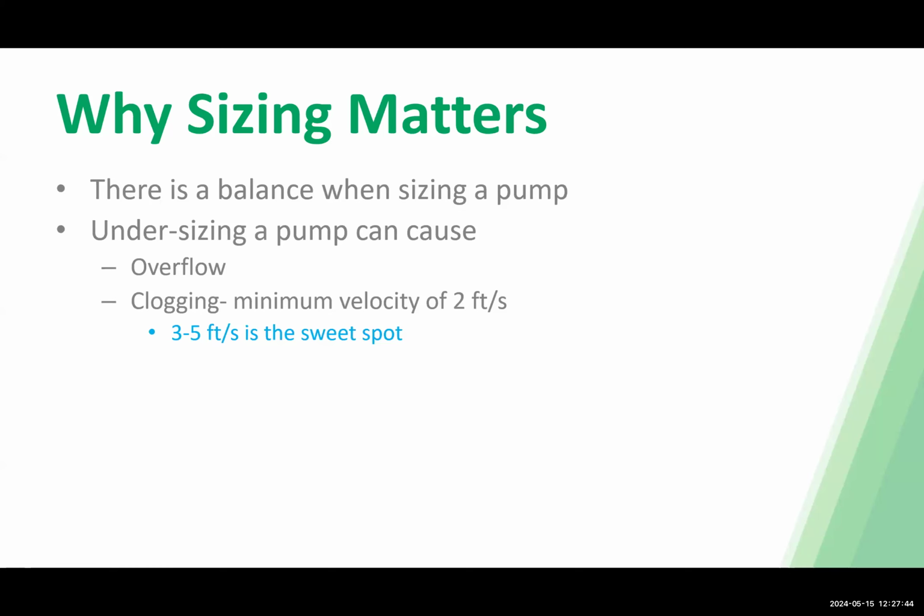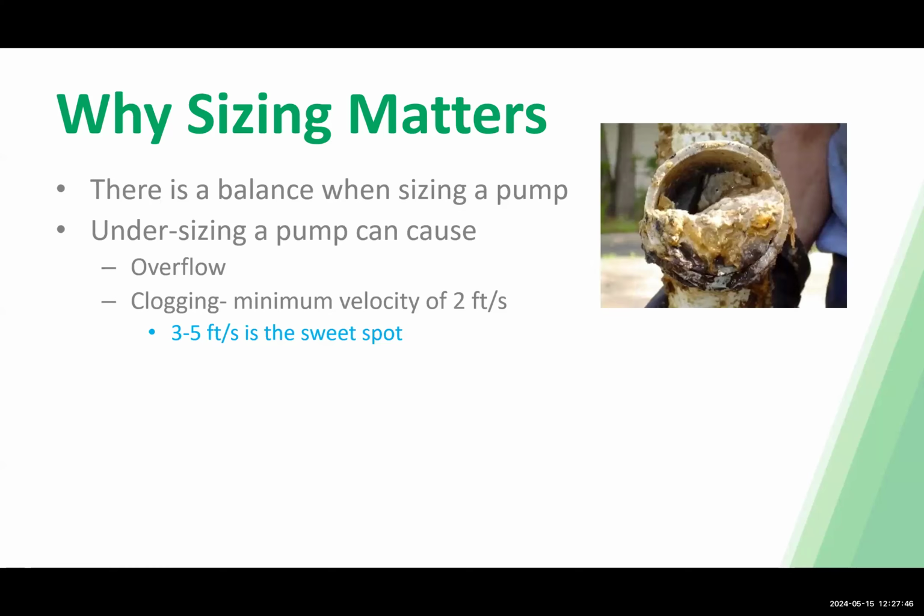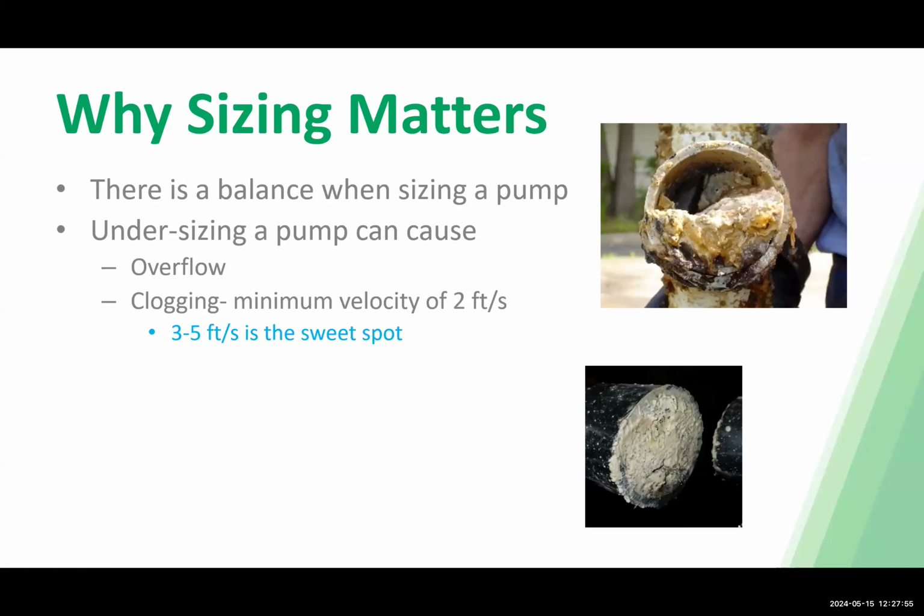of clogging issues. This is actually an example of a pipe that has slowly clogged up due to the velocities not being met. And then another example of a pipe that has actually fully clogged, and that pump just cannot overcome the pressure that is being put back on it from this clogged pipe. So no one really wants to go down and dig these pipes up and replace them. It is not a clean job.